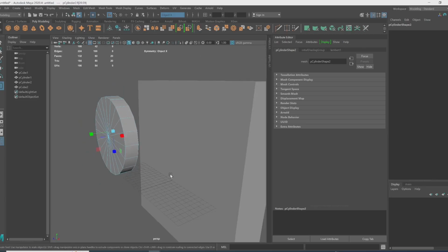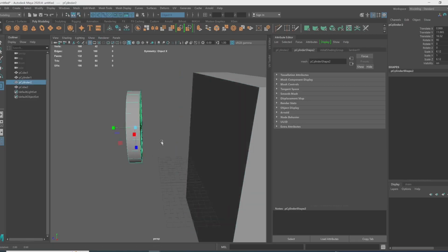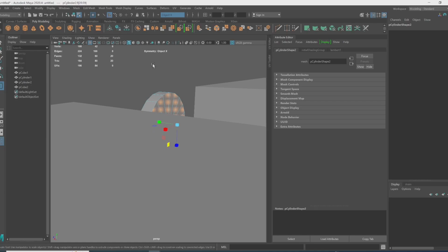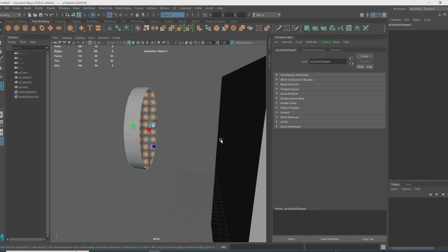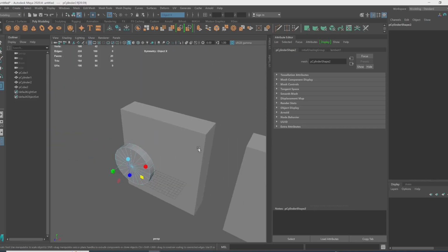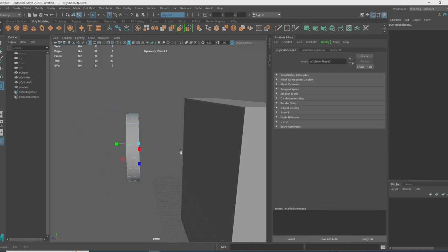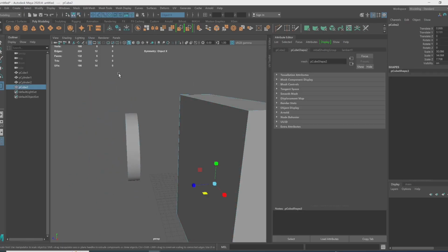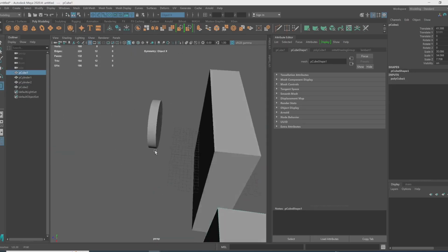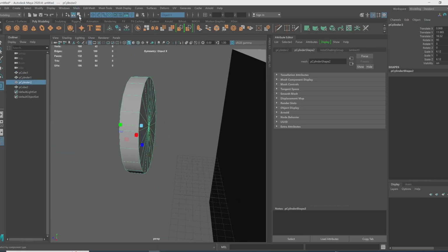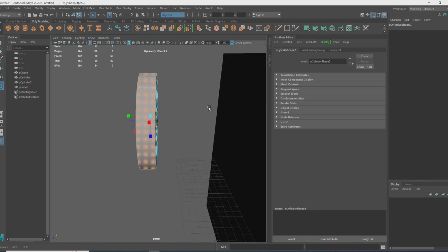So in this case, we're going to be checking what happens with the Boolean in terms of difference, right? When you use Boolean with difference, there are going to be some problems when you export the mesh after doing that. I want to see if this actually happens in Maya 2020, because 2019 had several problems with that. So we have this model and this other model, and we're going to export these two meshes in two different modes to see what's going on and to determine whether our assumptions are correct or wrong.